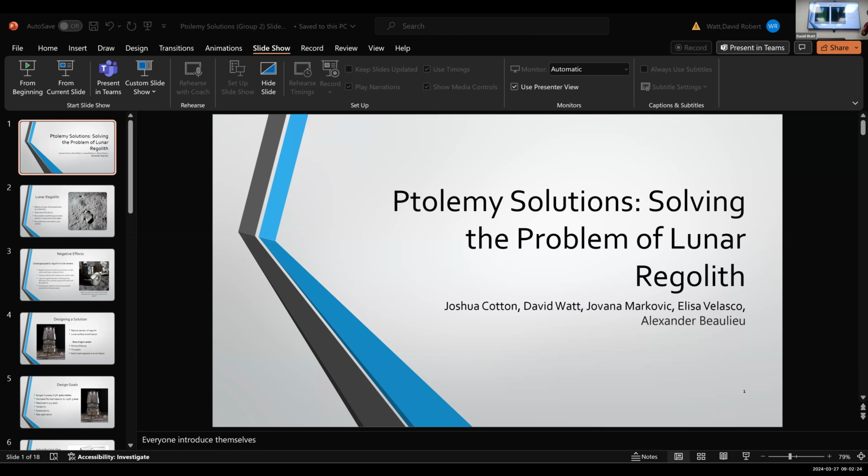Now, essentially, by adding the tarp, we're spreading those initial kick-ups of dust further away from the lunar lander. So in theory, that same amount of regolith will be spread amongst a larger volume, which will decrease the amount of contact density with the lunar lander itself. Through our math, while very crude, it came out that under these assumptions we're reducing contact of the regolith with the lander by about 49%.